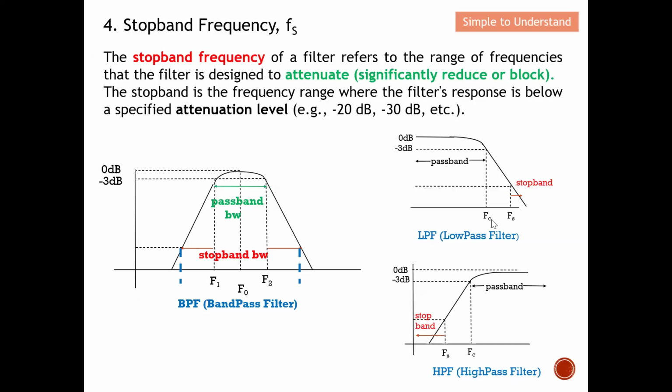Okay, this is a practical world. For a filter, you actually have practical limits. We don't have a transition directly from pass band to stop band immediately. So this is the reality of filter design. We have a transition. We call this the skirt of a filter. Ideally, we want it to be as steep as possible. However, this may not always be possible. So we have this stop band to indicate that after this frequency, we are very, very confident that the signal will be removed.